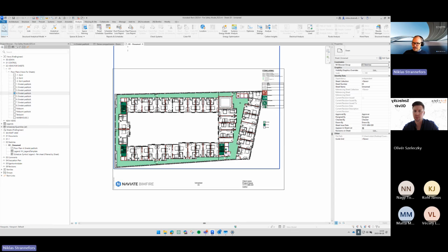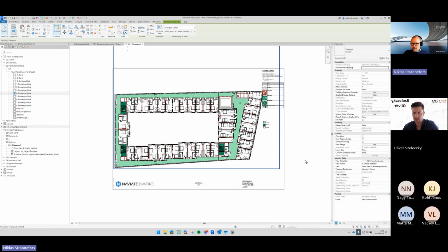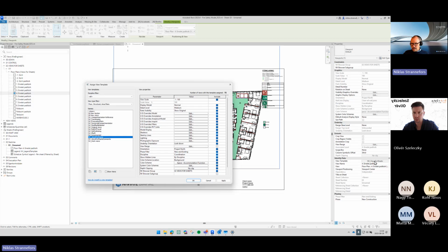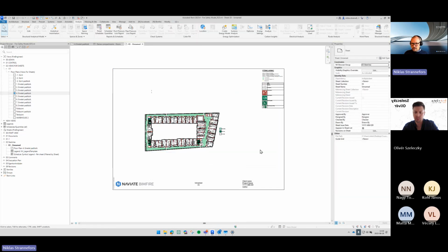even better. So we can select the view even here in the sheet. We can select it and then go to the view template because we're selecting the view and all the information. So this barely fits. Maybe you should go to 1 to 200 in the sheets. So once you drag and drop, it's here. We go to the views for sheet view template. We can change the scale on every one of these to say 1 to 200. If it's smaller, now it's better. We can make it fit, or 1 to 150 or something like that. I'm gonna leave it in 1 to 200.